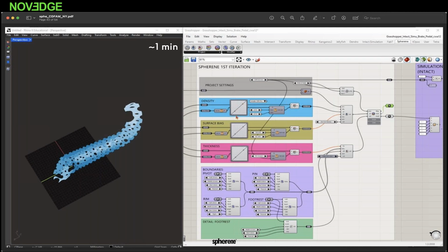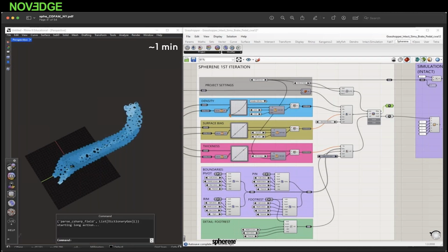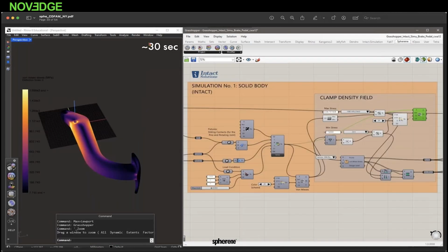Very easy to solve in Grasshopper. Just put in this curve modifier and drive the density at a specific point, adjust that. So we make the mapping, we remap the values so that we fill up this space that we had before. By the way, here you see the time, how much time this took.